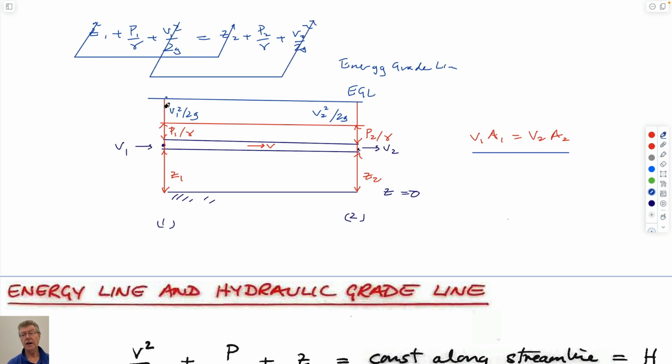And so these heights here that I didn't label have to be the same. And since Bernoulli from upstream to downstream in this energy grade line equals constant, and it equals the value of our energy grade line. You know, we could choose our datum anywhere, right? The datum could actually be above us if we wanted it to be. And so by definition, if this has to be equal to constant, then the pressures upstream and downstream have to be the same, by definition.